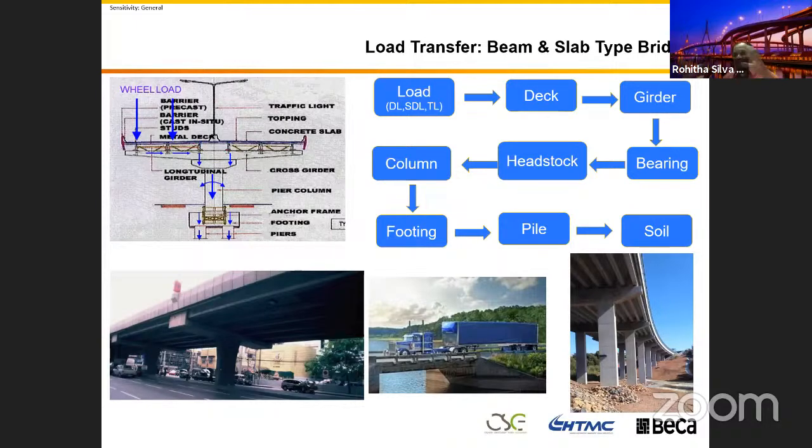The reason is we put that load after the bridge deck is hardened. If you design this element as a composite section, then whatever load you put on the deck after the concrete gains the proper strength, the deck will act not like an individual beam but like a composite section. It has more strength, and that composite section will carry the load.